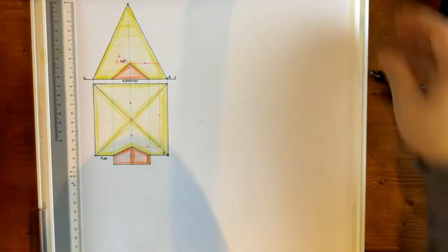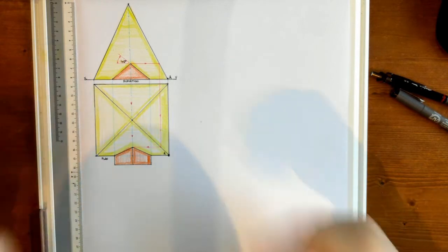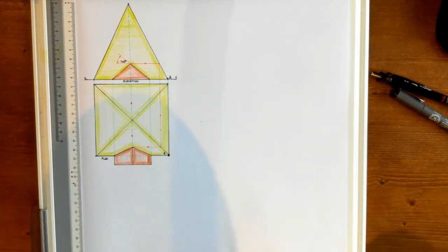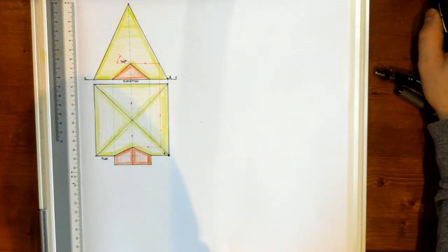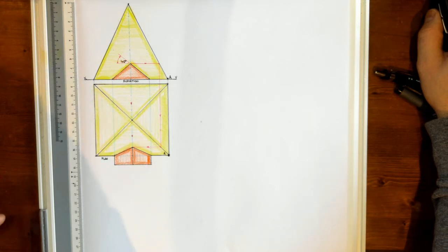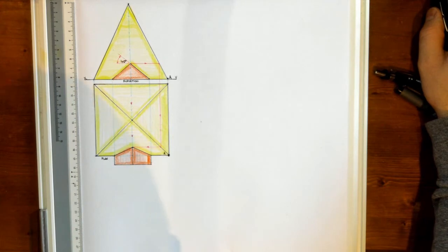Now, where do we want to go from here? Well, the first thing, like the previous questions, is we want to find the picture plane. In order to find the picture plane, we must find our spectator now. We're doing this a little bit in reverse from the previous day. In the question it said that the spectator is located 60 degrees from corner A at a distance of 8 meters. In the scale of our question, 1 is to 100, that 8 meters is actually 80 millimeters.